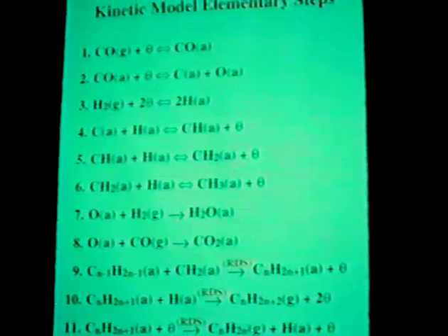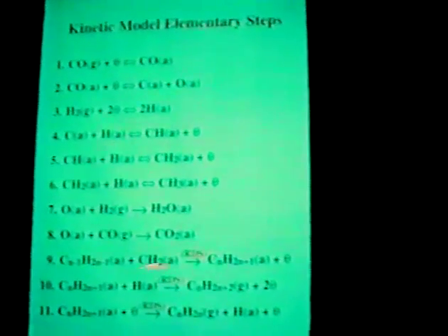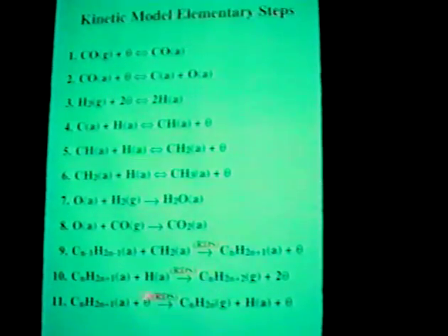Some of the approximations or assumptions that are made here are that adsorbed molecular CO is the most abundant surface intermediate. It's also assumed that the propagation and the termination rates are slow compared to the other reactions, and in this respect, they are co-rate determining steps.